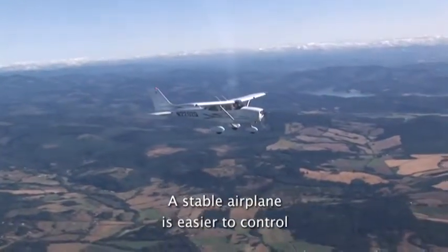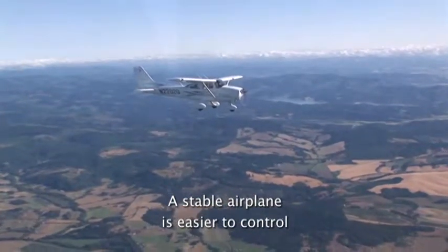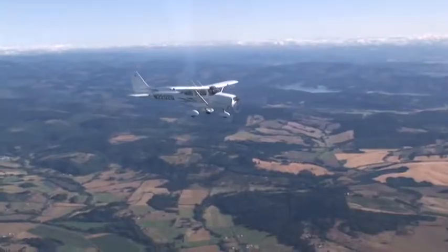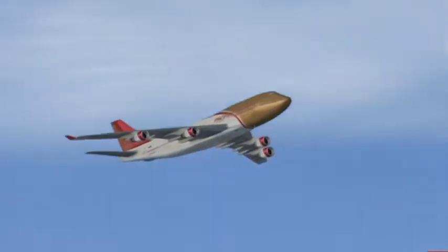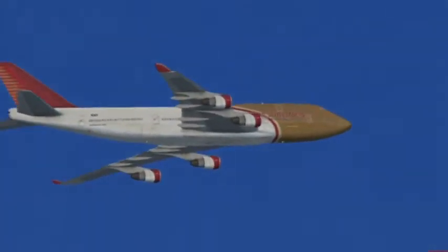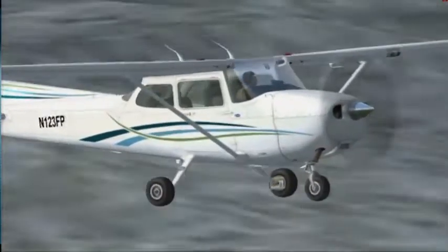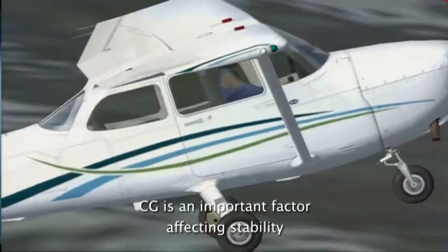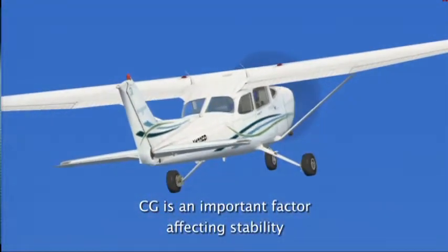A stable airplane quickly returns to its original attitude, and this is called positive static stability. A neutrally stable airplane normally stays in a bank turn or will eventually return to level flight. It has no inclination to make a bank steeper or shallower until you, the pilot, make the control input. If the airplane is not stable, you can get into some real problems with the center of gravity and aircraft loading.